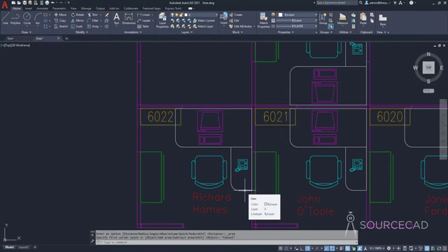That's one of the biggest problems with this area tool. If you don't have a perfect edge, then you need to ensure that this object is just one single entity. In this case, this one is. It's just one single polyline, but not this one. In this case, I need to make an extra polyline at least here and then combine it all into one unit, and then I can find the area. So there is a little bit of work involved in order to find the area, and hence this is not very recommended when you want to find areas of multiple regions. But anyway, I'll do that here, and then I'll show you an easier way of doing the same thing.